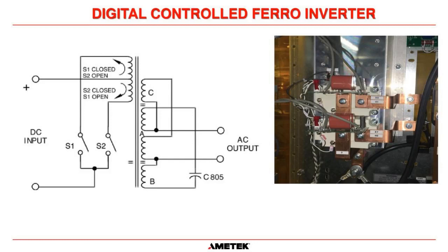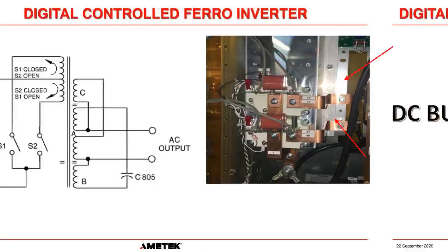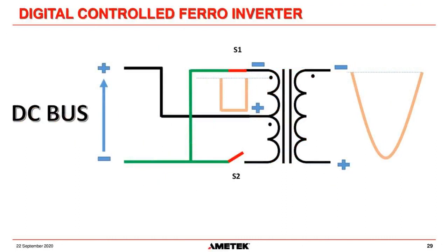This is a 10 kVA bridge right here. There's only 2 transistors required, and a small circuit board mounted to each one for the drive signal. And the capacitors you see right there are what we call snubber capacitors that protect the transistors from switching transients. So we're back to using a switch here to turn DC off and on.